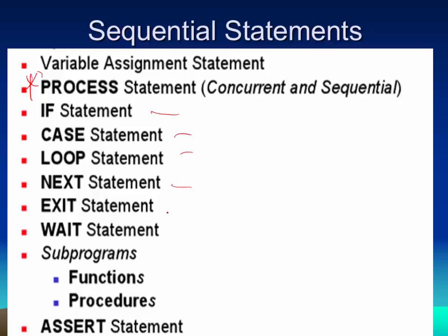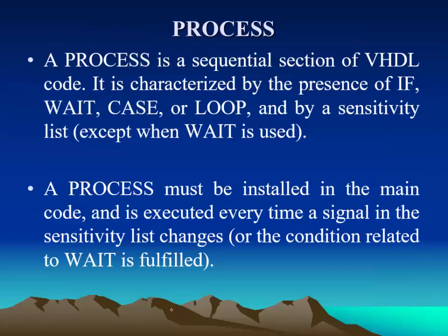We have next statements. We can exit, we can wait. Now the wait we don't necessarily use very often. Not in synthesizable. We can have functions and procedures, which we're not going to get into in this class, where we can actually make things look more like code.